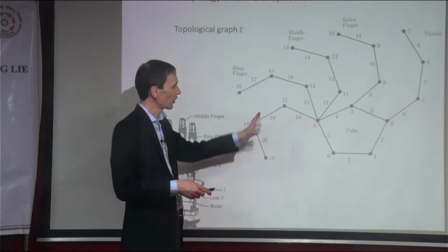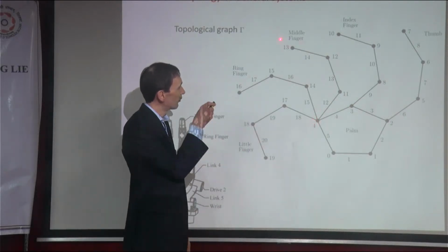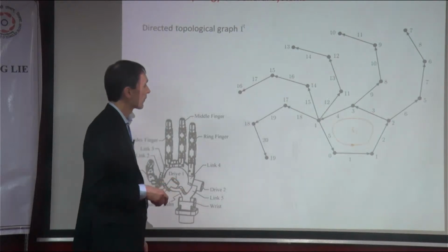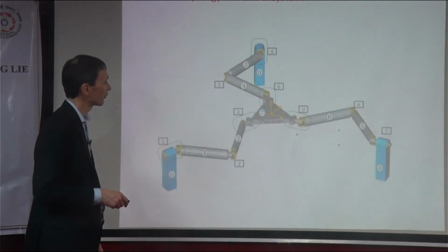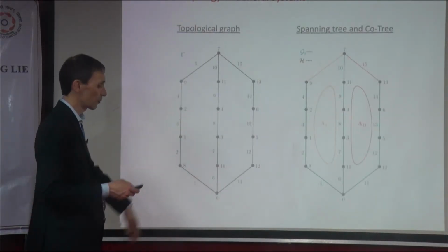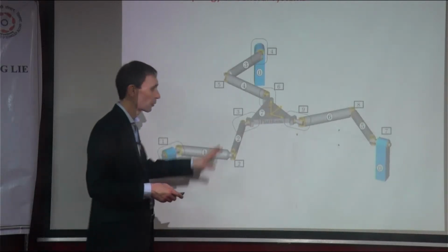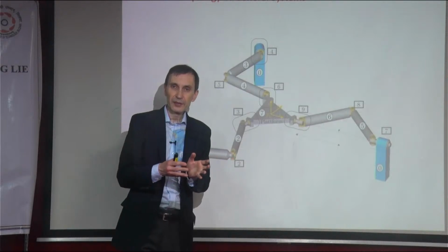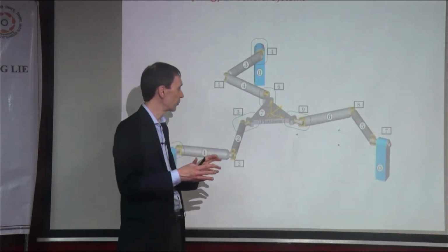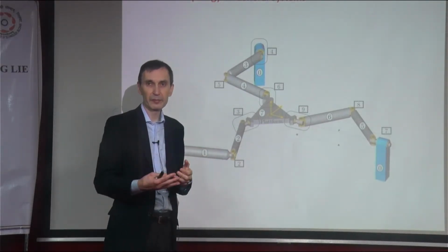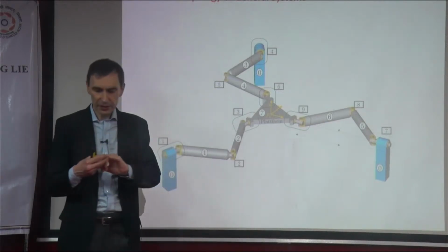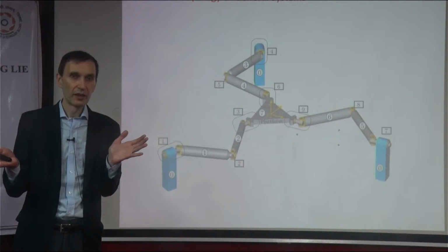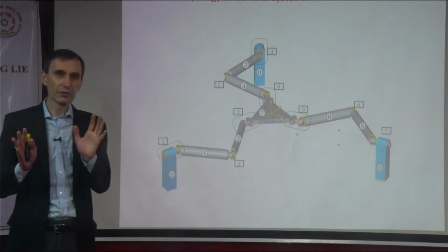So this is a kind of a mixed system, right? Because you have, of course, an open kinematic chain here, and then you have the closed loop system here. If there's one single loop, then of course you can open this, and the same goes with this mechanism. And you see for the PKM, there's always a nice structure, and this structure is what we're going to employ for the modeling of the PKM, because there's a whole theory for modeling general closed loop systems, and that's a bit mind-boggling. It's just not that easy.